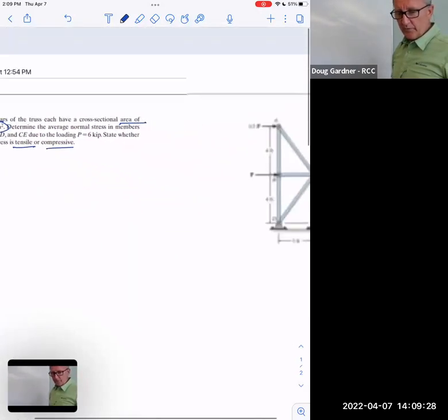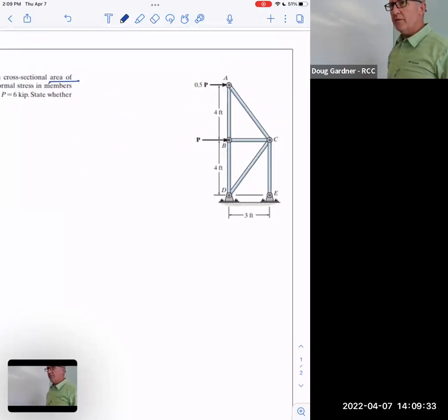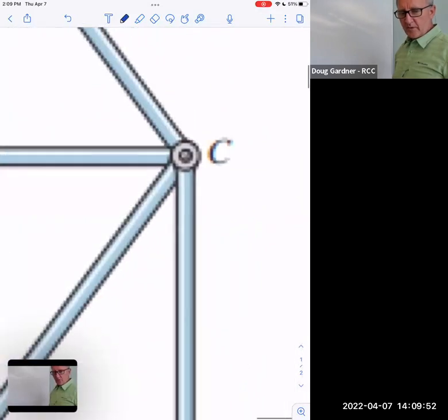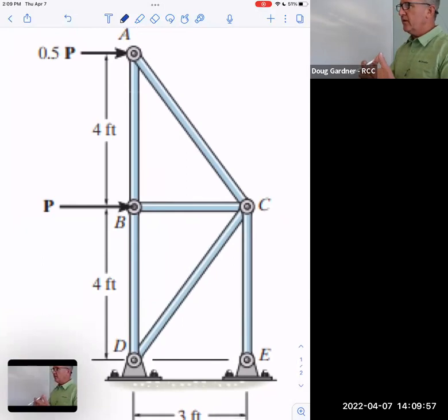But again, we're close to actually being able to really design stuff now. Literally somebody says, I want you to make this thing for me, and you're like, I can do that. I can make all the calculations. How much weight is it going to have to carry? Then you work the weight all the way through it, and you look up in a table based on PSI calculations. You know exactly what size material to use, and you know how strong the weld at that joint needs to be. If that's a pin going through it, holding all three of them together, you could figure out how much force is going to want to shear that pin off and so forth. That's kind of cool.